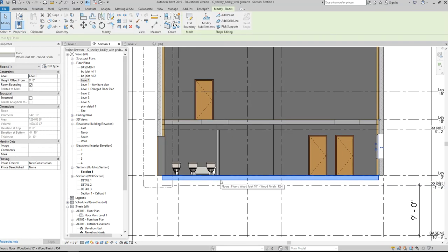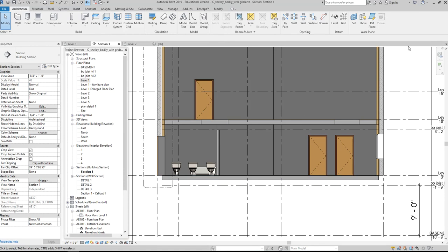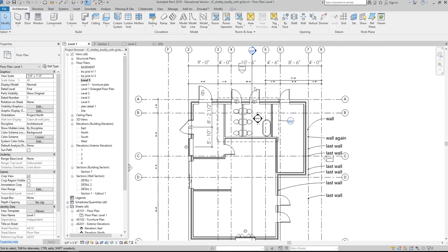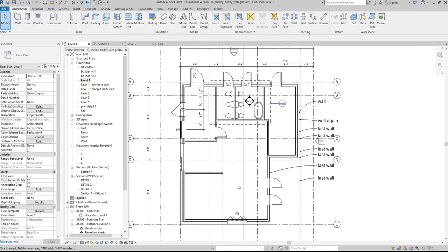create a structural floor and then to create a second floor that is the finish that goes on top of it. So with a lot of projects, you essentially have two floors that you draw, in the case that you have different flooring for different spaces. Right? So you have a structural floor and then you have a finished floor essentially. So what I would do here is I would go back to my level 1 and I would create a new floor type.